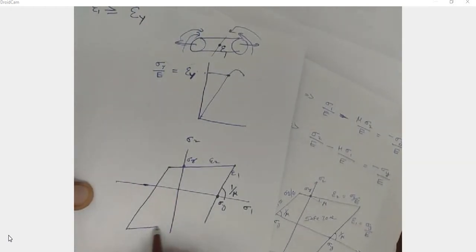And this one. So I got this type of rhombus structure, and inside region of this rhombus is a safer region and outside is a failure zone. And in the 3D case, this is the equation for the 3-dimensional stress system or tri-axial stress system. In the case of 3 dimensions, we have 3 principal stresses: sigma 1, sigma 2 and sigma 3.